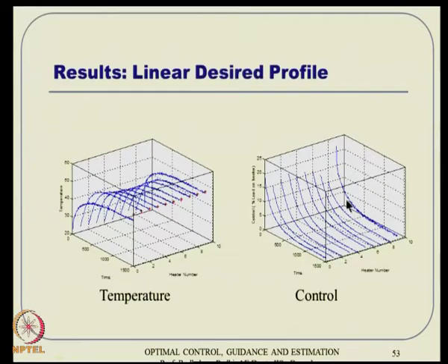This is the final result. Ultimately we wanted to have uniform temperature and all that. At the very end, at the boundary, it was not able to do a very good job. Obviously, there is an insulation problem and implementation issues and all that, but nonetheless it was able to control in a very good way. It was coming to the constant values irrespective of where you start. So, if you really want a constant profile, roughly it is doing the job.